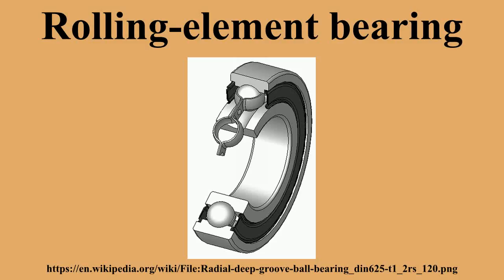Typical rolling element bearings range in size from 10 mm diameter to a few meters diameter, and have load carrying capacity from a few tens of grams to many thousands of tons. Ball bearing. A particularly common kind of rolling element bearing is the ball bearing. The bearing has inner and outer races between which balls roll. Each race features a groove usually shaped so the ball fits slightly loose.